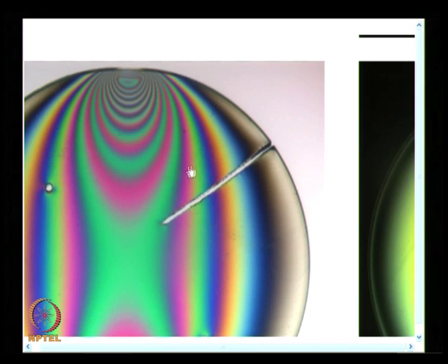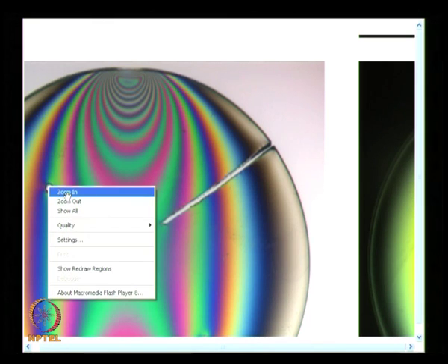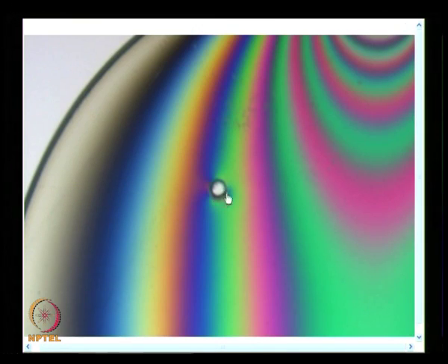And if you take that kind of care, what this fringe pattern shows is, when I have a slit made, the fringes are not disturbed, and you have a slight difference here. This is a hole made, you find, though the hole is made reasonably well, there is some small disturbance. It is not as good as what you had with the slot. So, the person who has made the hole needs to improve his process, because you have some small disturbance. So, even this could be eliminated by careful machining.